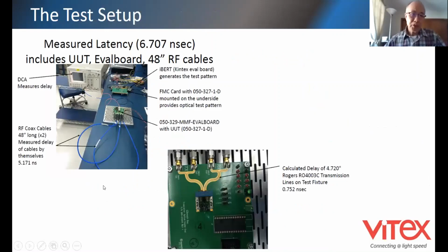Now here I took some pictures. It was done before. You can see this is a generator with a reference transmitter, right? And with some cables. I don't care what the cable is because this whole block is going to be calibrated out. Then the transmitter drives the receiver here, right? This is the DUT. Those blue cables I call the loopback cable, right? And then going back, this cable goes back to the transmitter, and the transmitter goes through this fiber, which I call A, and then B is somewhere here.